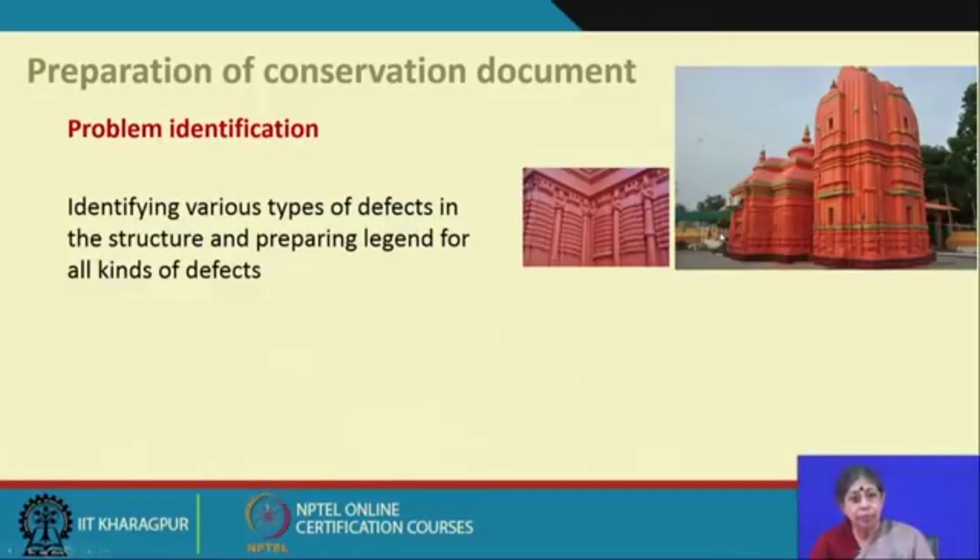The repair work or the maintenance work which has been done is with a synthetic enamel paint. It is actually stopping the breathing of the structure, it is interfering with the authenticity of the structure, the color of the structure, the material of the structure, and in the long run it is actually making new types of details which are not a part of that.